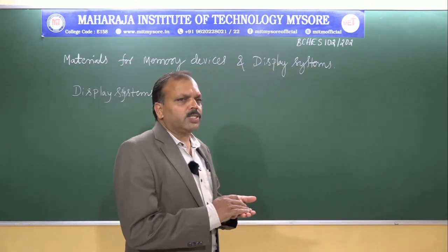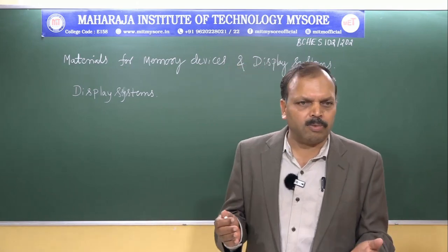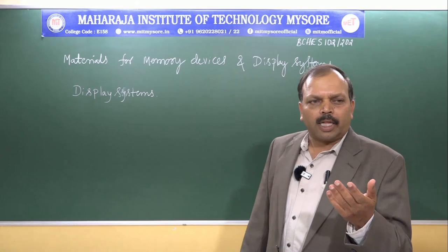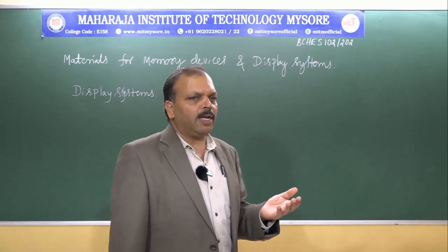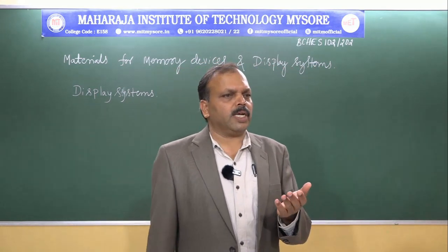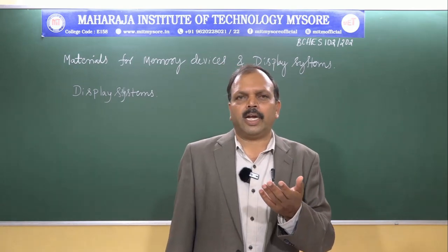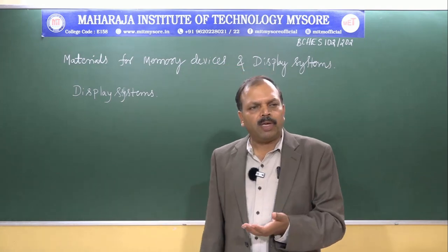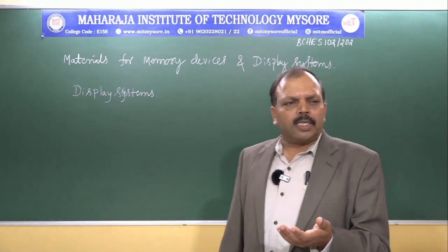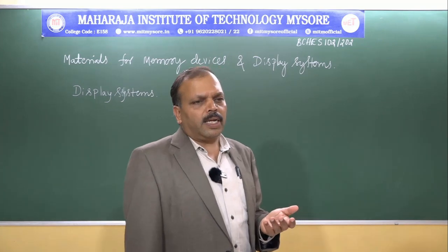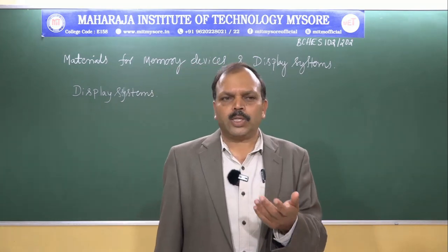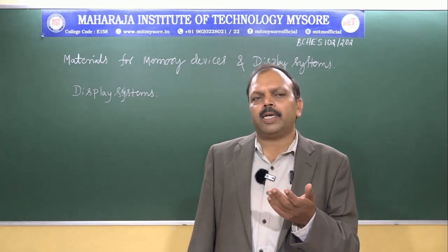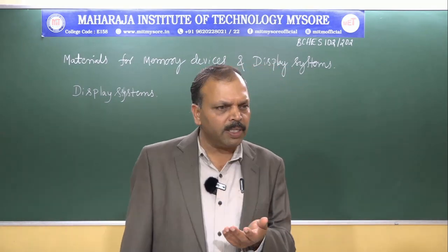Solubility wise, PVK is soluble in a wide range of solvents, which makes it easy to prepare solutions in the polymer processing. Thermal stability wise, PVK has a high glass transition temperature, which means that it can withstand high temperature without degrading. Coming to the applications of PVK, it is used as a resist material, particularly in electron beam and X-ray lithography. PVK is used in the fabrication of light emitting diodes and even laser printers.